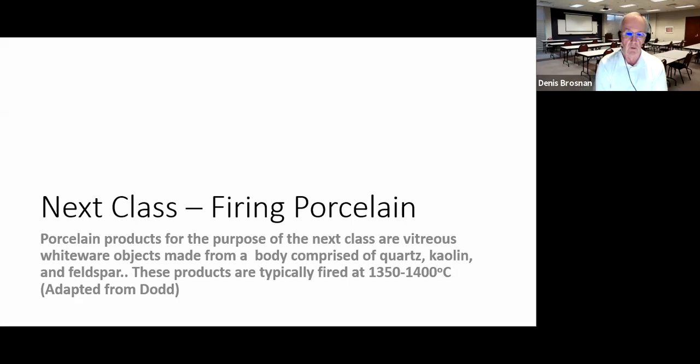Well, today, even with crude products like heavy clay products, I've tried to make a connection between phase diagrams and transient phases, the initial liquid formation and forming these products created by potassium, about the fact that we can form a couple of different glasses in firing some of these products, and they can be identified as immiscible in most of these heavy clay products. We don't naturally know that, we don't see that, but that's the deal.